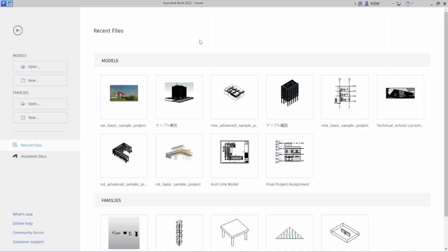In lofting, whichever we created, either a vertical lofting or horizontal lofting, and as we added patterns to it, we'll learn how to apply thickness to those patterns to make it like a panel. For that, we have another family template called curtain panel pattern base. This is the template that we will learn today.